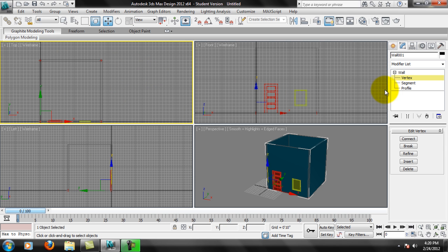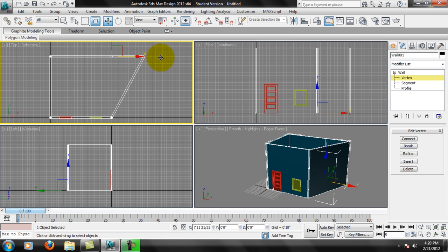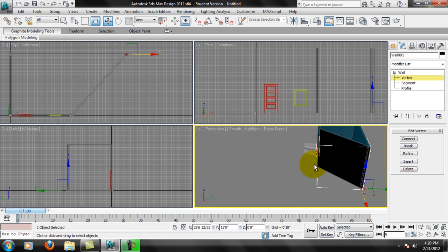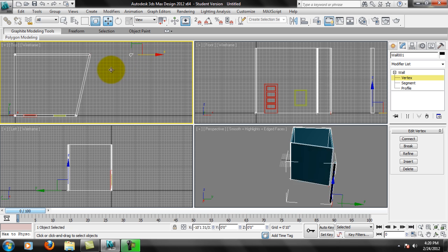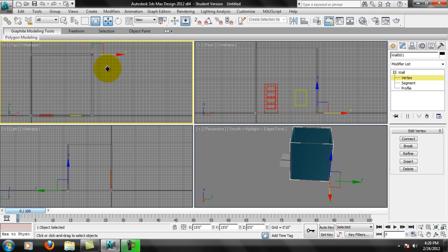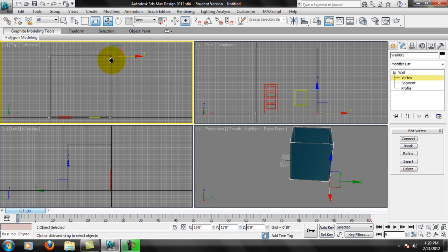Notice you can control the vertex of this point, and you see there's a vertex in every corner. So by moving that vertex, I can control my wall there. If I wanted to do any modification to that wall after the fact, I can move the vertex there, but again, be cautious that once you move that from being nice and straight, it can be difficult to get back unless you know the exact point. So when you're modeling this stuff, if you decide to use walls, be careful to maybe jot down where your location is at that point.